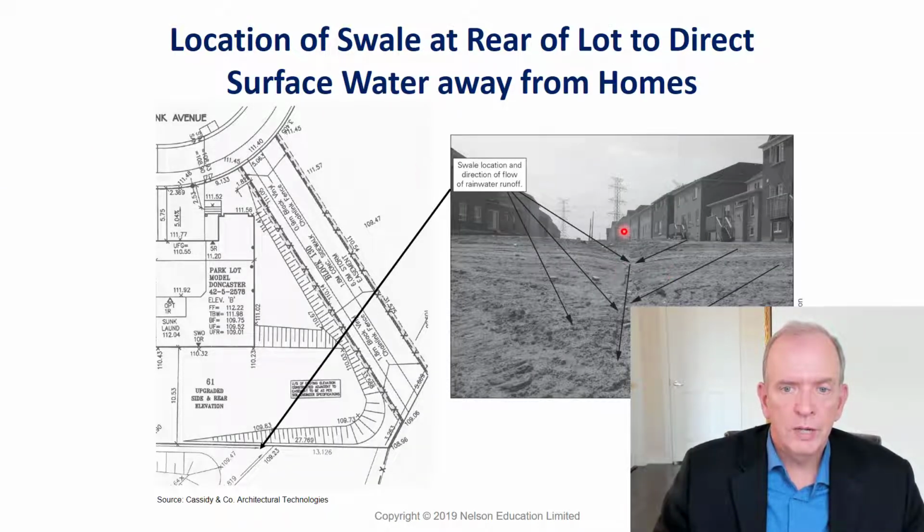This is a swale that I was mentioning. So this line with an arrow, that just means that the grading has been designed so that the grade slopes. And if you remember, this is sloping here quite steeply. So this is where I'm standing somewhere around here now, taking the picture, and this is kind of looking this way. You can see that the water from both sides is running into the swale, and that's going to run here, and the tributary river is over here.